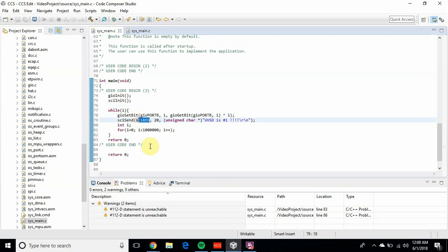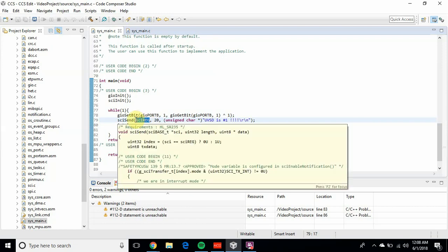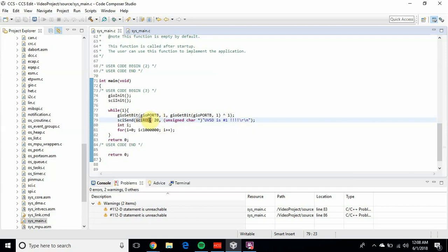So the first thing we're going to do again is set up the SCI register. For your LS12 board, it's going to be SCI reg. If you are on an LC43 board, which is the older development board, I believe it is SCI reg 1. This varies from board to board. It's just the terminology associated with the specific board, so different ones have different built-in register names.